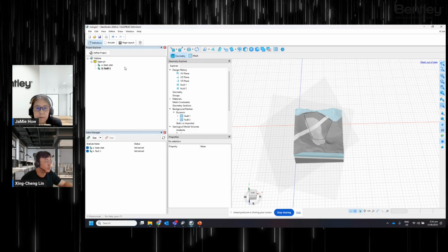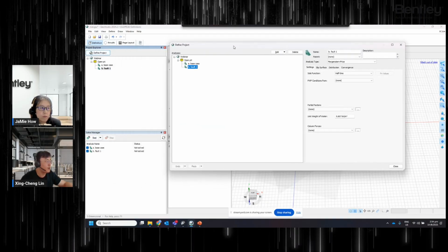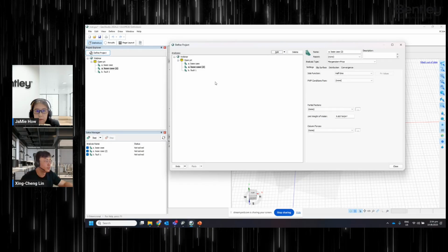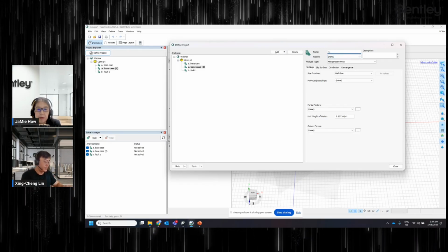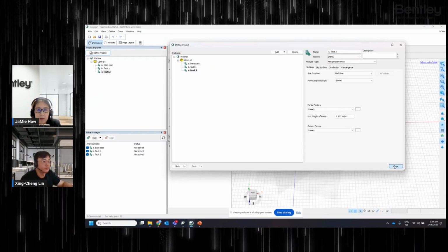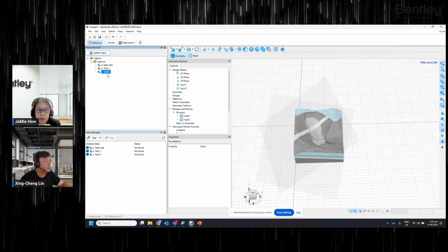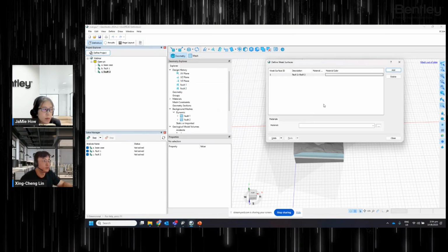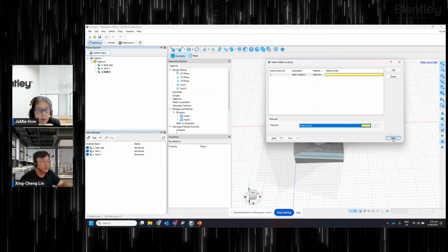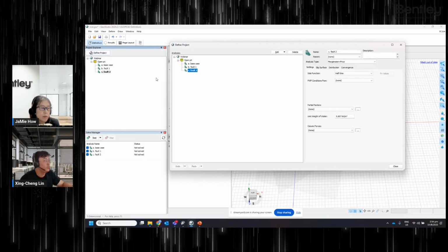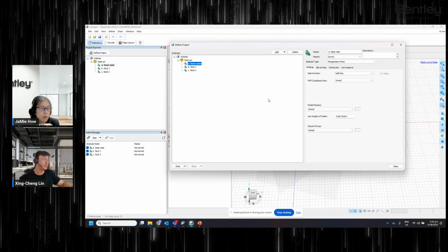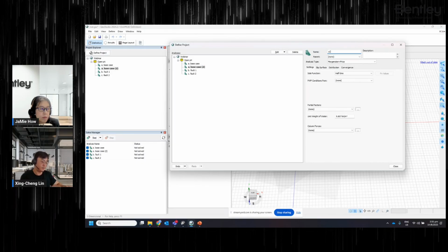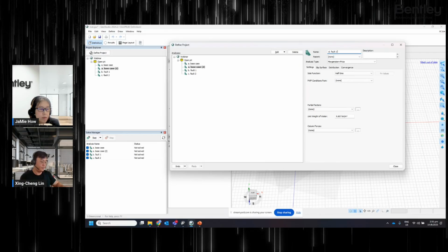In this case, we're going to go again to define project, and once again clone another phase. We'll rename it to case number C, and in this case we have only fault 2 active. So likewise, we're going to go to settings, define weak surfaces. In this case, we'll add fault number 2 and choose the corresponding material. And finally, the last case, where we'll consider the two faults actually adding together. So likewise, clone case number D, and we name it fault 1 and 2.